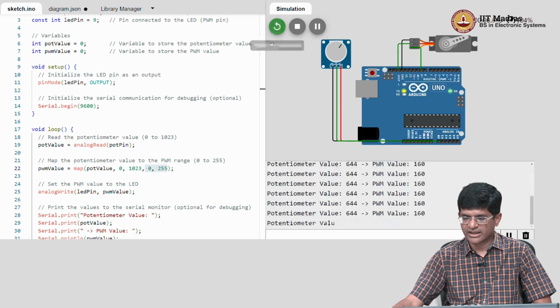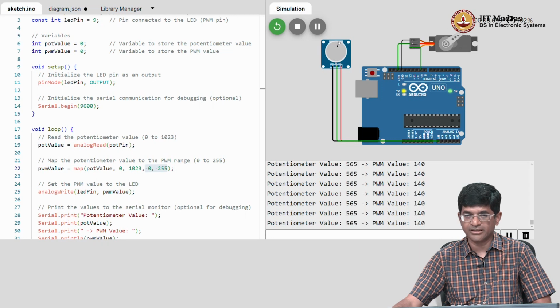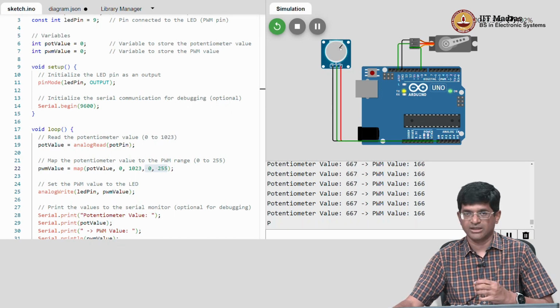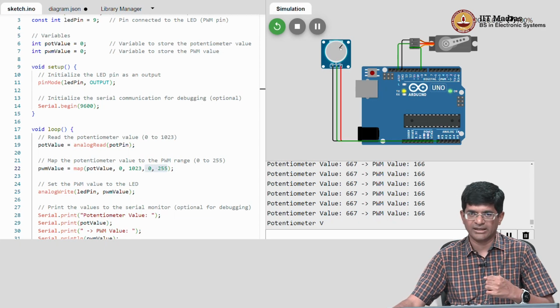So in this particular case, when I run this, I can see that as I move this thing, I can turn the position to which the servo motor is tilted. It has a limited range of operation. When I go outside that range, it flips out and ends up with the wrong value. Similarly, when I go outside the range in the other direction, it just saturates somewhere. But within the range that I have, I can get it to move around just by turning the potentiometer, which is changing the analog value being read in. That in turn is giving a different PWM value to the servo and changing the orientation at which it points.